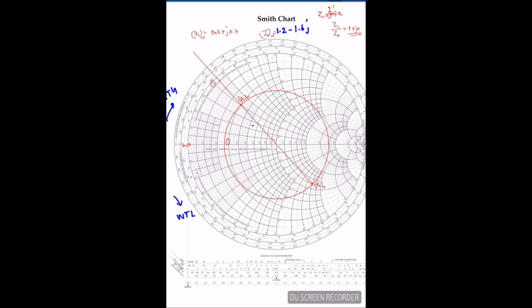So the next step is from this plus jX. If I add minus jX to my transformed admittance, both terms will cancel out. So I'll get ZL equal to only the R term; this reactance I can cancel out. If I make it 1, now I have made my admittance the properly matched admittance, that is 1.